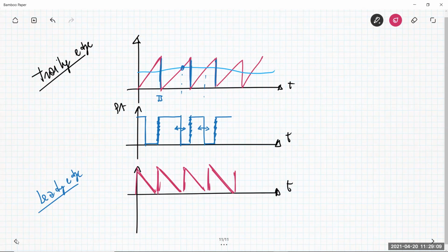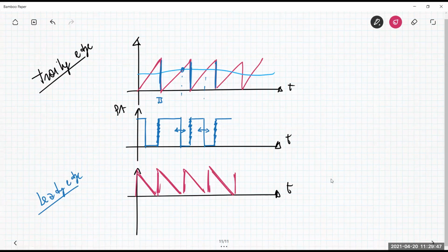And there are many other modulation techniques, like random modulation, chaotic modulation, density modulation, etc. These are typically for communication channels, but can be employed also here. But I have to say that 99% of the time, unless you require some specific and particular situations in application, pulse width modulation is what you will find in your application.